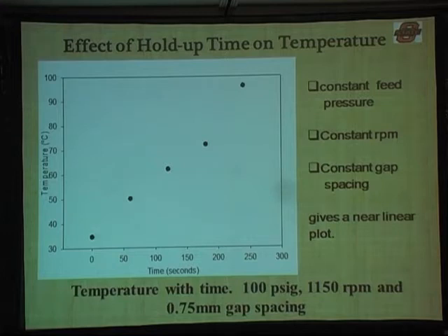The spacing needs to be fairly tight. We're doing most of our experiments at a little less than 1 millimeter for 5,000 centipoise. So we don't want water mixed in with our solid material here. Lower viscosity would present a limitation for us. A way around that is to recycle the solids.